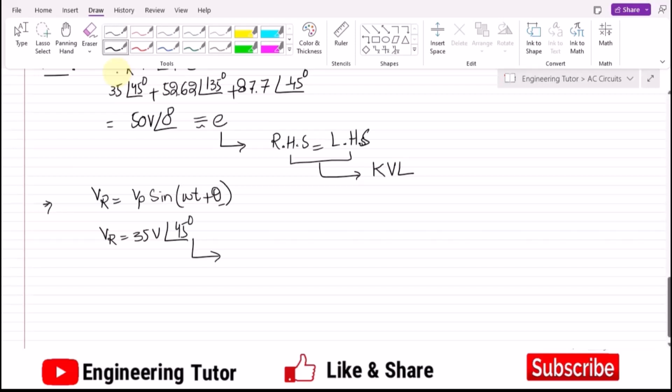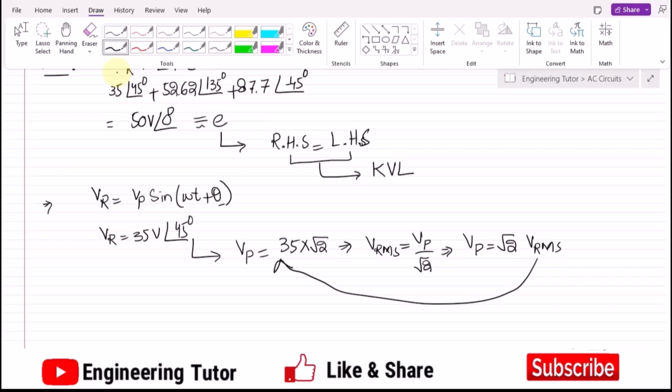From it we can see that the peak value here is 35 multiplied by the square root of 2. Why? Because the RMS value is always equal to Vp divided by square root of 2. So now in order to find the value of VP, we have to multiply the square root of 2 with the RMS value. The angle, 45 degrees, is also mentioned here. So we have to find this value and then put it here. Also the value of theta is given here.